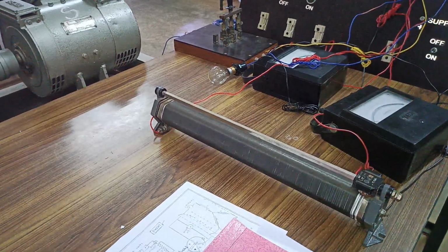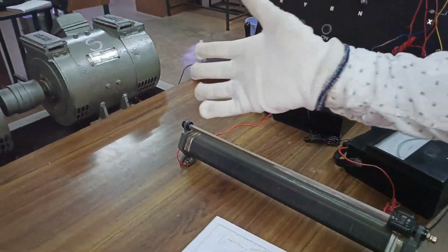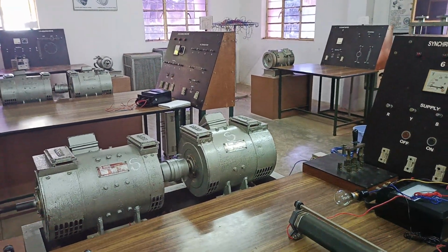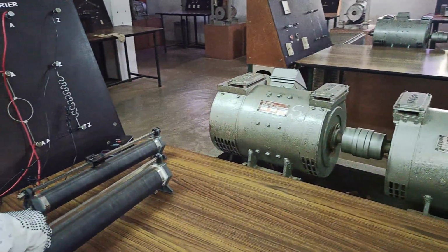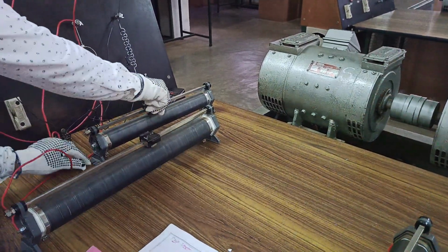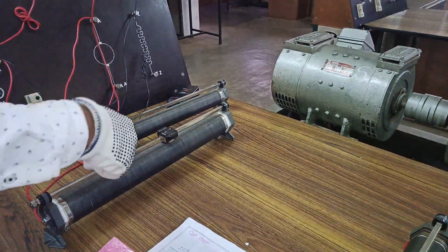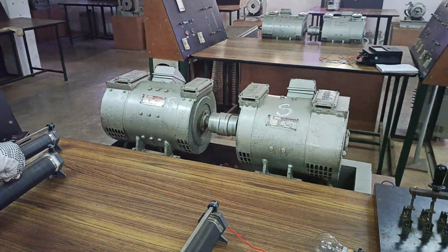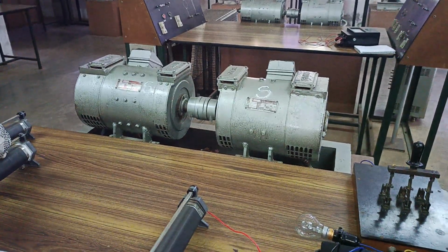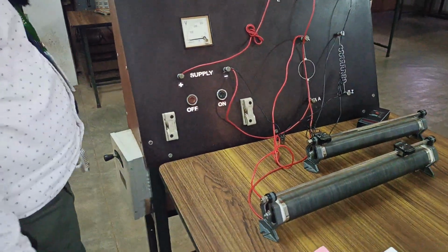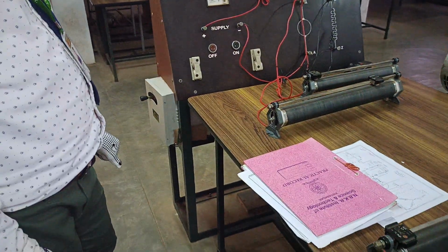This is something we have to do with a little more patience, and we have to excite this prime mover at a constant speed with multiple loads. After running it, we have to bring this prime mover to the initial condition. Okay, so now we are bringing this to the maximum resistance, and this also we are bringing to the initial. You can see here the motor runs very slowly. Now you can see I am increasing the resistance in the armature, so it will run at the minimum speed, and we have to remove the supply. Automatically the prime mover excitation is removed.